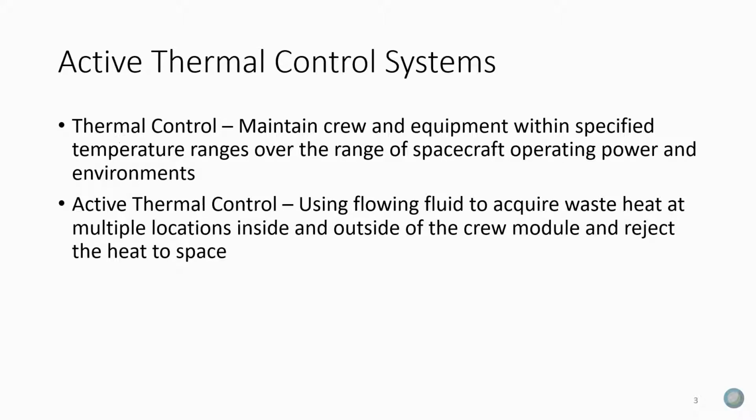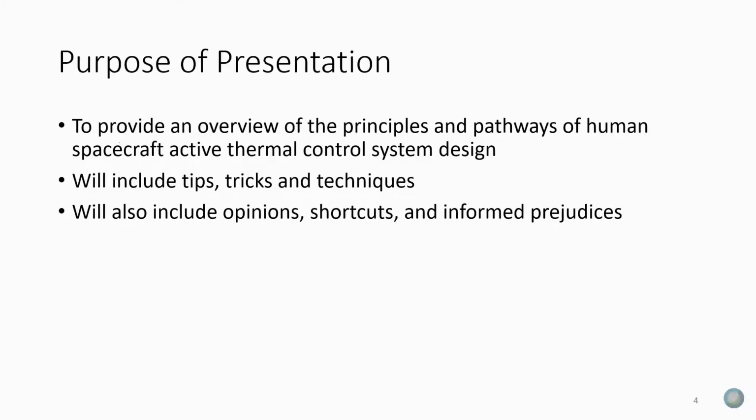We pump the fluid, acquire heat through the fluid, take it out to radiators or someplace and reject the heat to space, whether it's to the vacuum of space using a sublimator or an evaporator, or using a radiator to reject it to the cold of space. So here we're really going to talk about active thermal control systems, because that's my field and that's what I do.